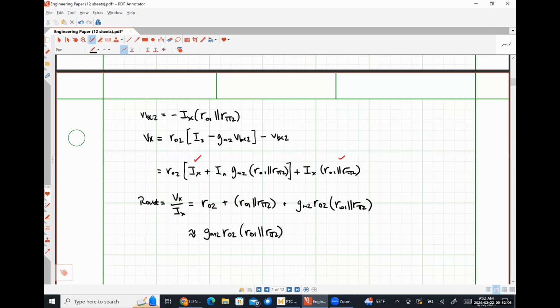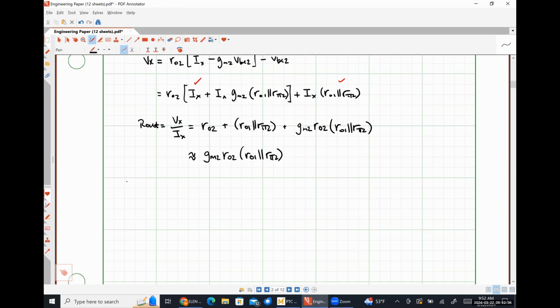All right, so input resistance, fairly straightforward. Output resistance, a little bit trickier, but realistically, it's damn near the exact same thing as stuff that we've done before. Looks incredibly similar to an amplifier with a degeneration resistor because that's kind of what it is. Now let's figure out our voltage gain. And to figure out our voltage gain, we are going to have to figure out what our short circuit transconductance is, right? Or we're not going to have to, but that's the method that I'm going to choose to employ because it's significantly less of a pain in the butt.